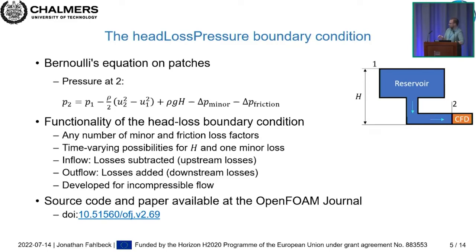My current studies also concern startup and shutdown sequences, and for this model scale, at least, we are thinking about times of 3 seconds roughly, but then it's just shutdown, but then of course you need to start up the machine, so say perhaps 10 seconds for this model scale if we can control everything nicely. For the prototype scale, this is supposed to happen later in the research project, so we have not started evaluating a reasonable time scale, but hopefully we can use this. There are a number of scaling laws within hydropower that we can use as a rule of thumb to get the first estimate of roughly how long the shifting times will be.